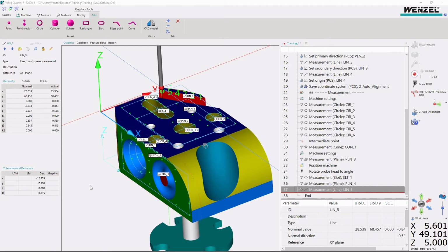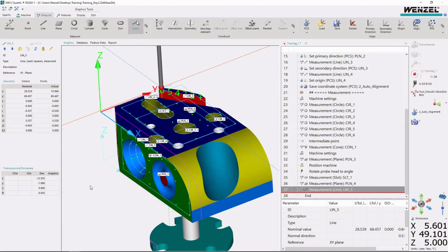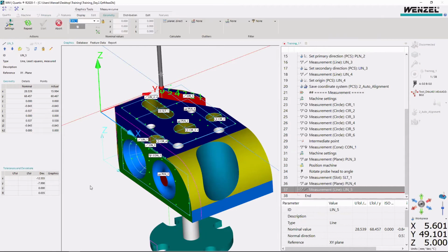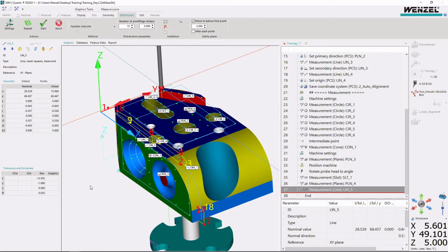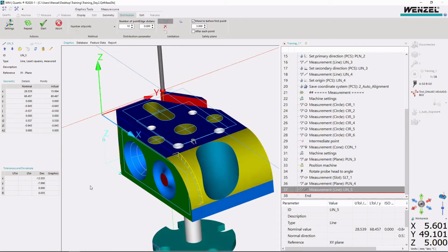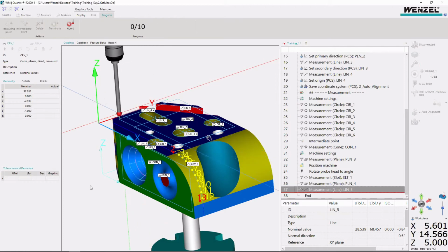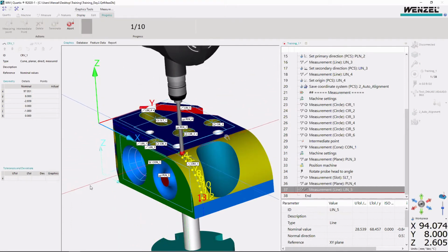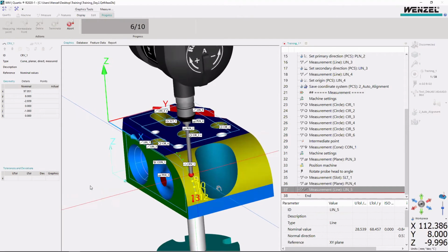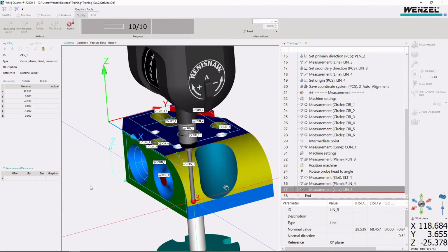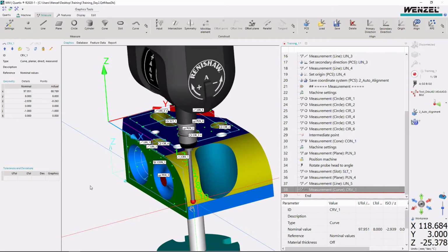You can rename it. And then I measure this curve. So click measure curve and then left click and then right click this curve. And then I only need a part of it, so set up a boundary. So delete it and then set up 1, 2. So these are my points. Okay. So what I can do is just start. So this is how we measure a curve.